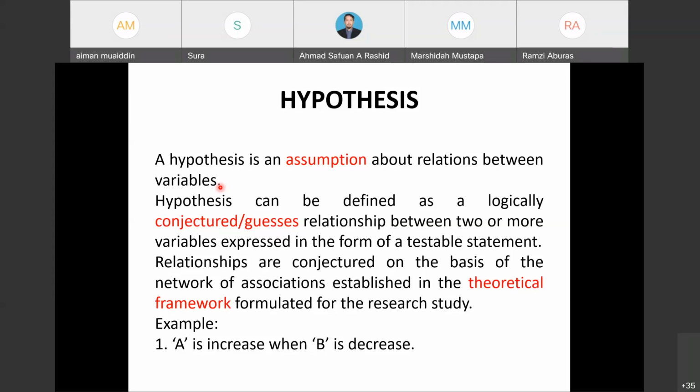Or if you want to look at the bearing capacity of a footing or foundation, you need to identify the width, the length, the strength of the soil, the soil properties, and also the load that you need to apply.